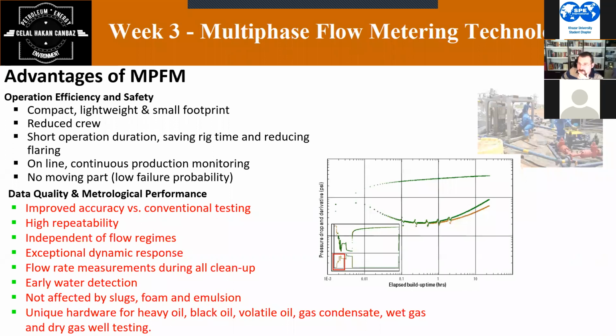Let's describe the PVT measurements in this case. So you take your fluid sample at the surface or in your reservoir. Okay, you take this sample to your laboratory to run certain experiments which describe the composition and the characteristics of that composition. So first of all, you can do the composition analysis. How many percent C7, up to C7 and C7 plus, mainly, I'm talking basically, or C36 plus. Okay, so you get your composition, the mapping of your composition.